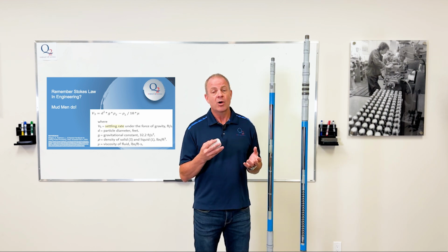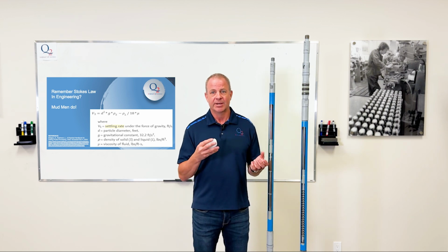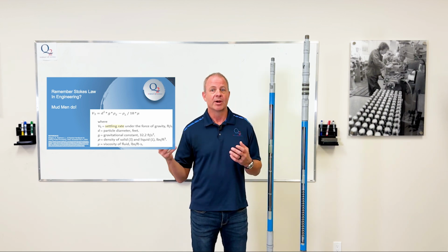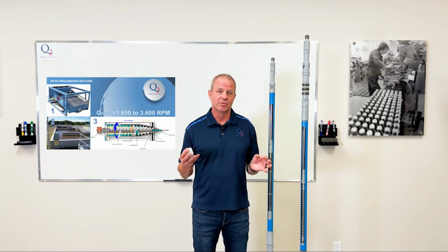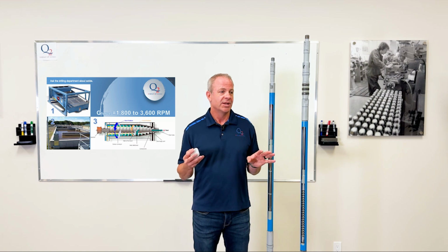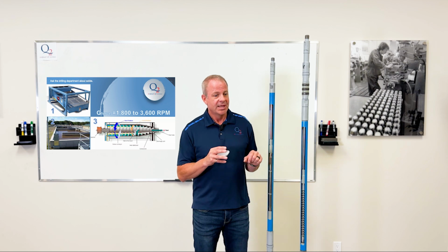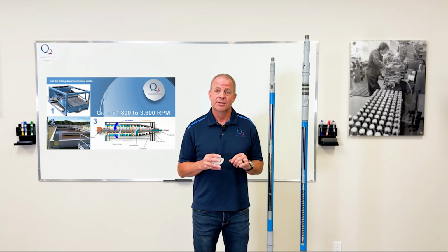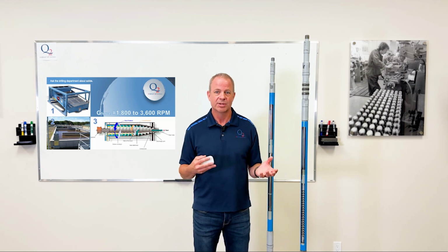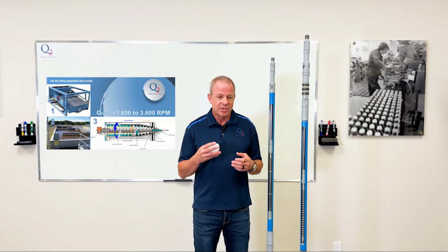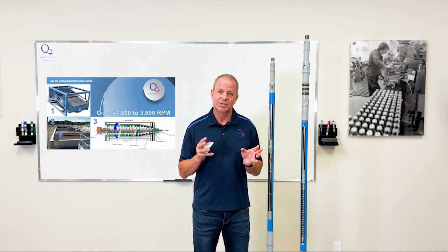And in our world, sometimes it's good to go to the other worlds like drilling and the environmental guys to understand how they separate solids. The drilling side is really interesting. The first thing they do is use shaker screens, right? They use elliptical shaker screens of certain sizes, and that takes out the majority of the solids. The second thing they do is use settling ponds or sumps. Back when I was on the rigs, they used sumps, but now it's tanks. That gives you the time you need to settle some of the solids. But then the really fines hang out still in there.